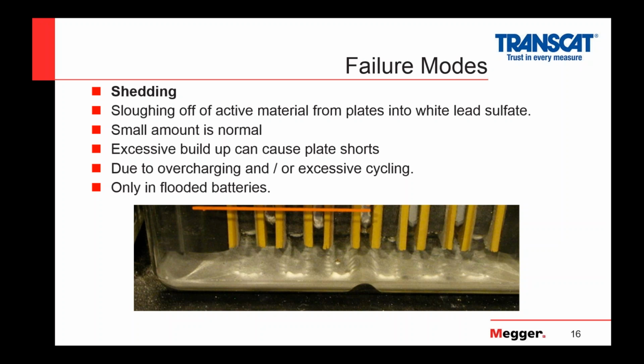As the material comes off, again, this is going to be accelerated by heating. As that material falls to the bottom, I'm losing active surface area. The impedance of the battery is going up. Now, if enough of this sheds off to where it goes up and actually touches the plate, it can cause the plates to short, and suddenly what you'll see is the impedance will drop along with the voltage as well. The key thing to keep in mind here is that typically we're only going to see a little bit of this, and it only concerns flooded batteries, VLA batteries.